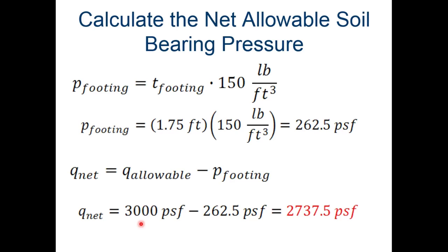So if I go back to that chart, on the first page of your guided notes, mine was sand, and then it goes across, that would be 2,000 pounds. So your number could be 3,000 pounds. If you look at that chart again on the first page, if you had gravel or gravel with fines, it's 3,000 pounds, and so on down the line, depending on what kind of soil you have. Depending on where you get your soil, for the most part, they're going to be either gravel through sand with fines. In Utah, all the years I've been doing civil, I rarely ever get any samples that are silt, clay, or organics.